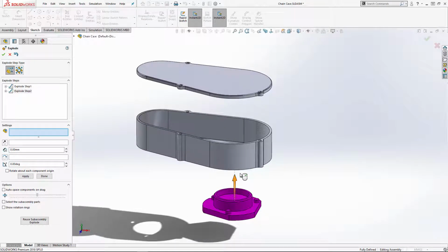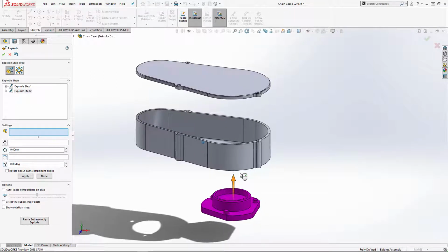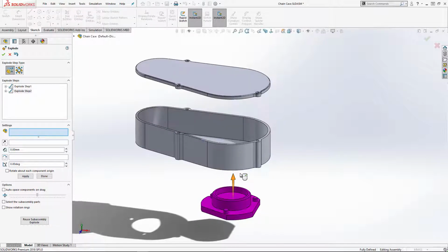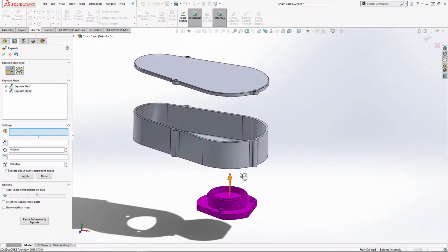The general rule of thumb is whatever angle you're going to view your part from in your drawing, so let's say we're going to view it from this sort of angle, you want to be able to see a little bit of daylight or a little bit of space between each component. That's to avoid confusion. If one component is overlaying the other one visually, it can lead to confusion as to what geometry belongs to one component versus the other one that it's shown on top of.